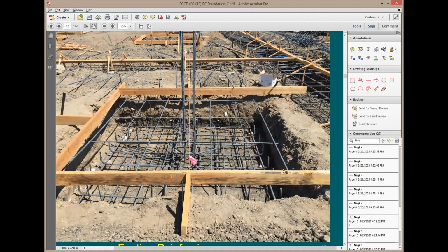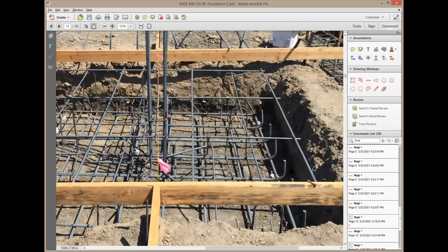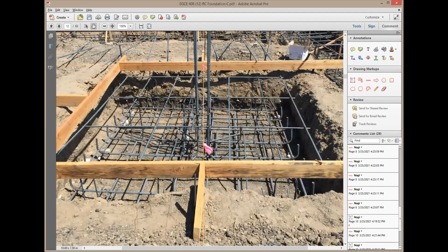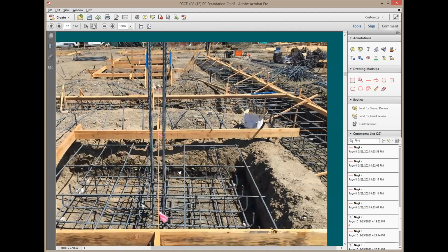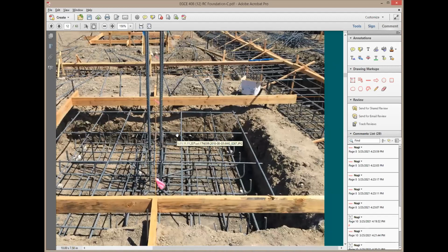I mean, having this through the soil or through a hole in the soil is going to be acceptable to us. Look at the rebars. The bottom rebars, you have them with hooks, right? Running across in both directions. And look at the top rebars. Now, these vertical rebars, you need to brace them. Otherwise, they're going to be collapsing on one side, or just falling. So you need to have some rebars in this direction, at least at the column location. And this can be the column dowels or rebars, right? That's why I need them. And this is the reason that the top rebars are not heavy. Yeah, go ahead, please.